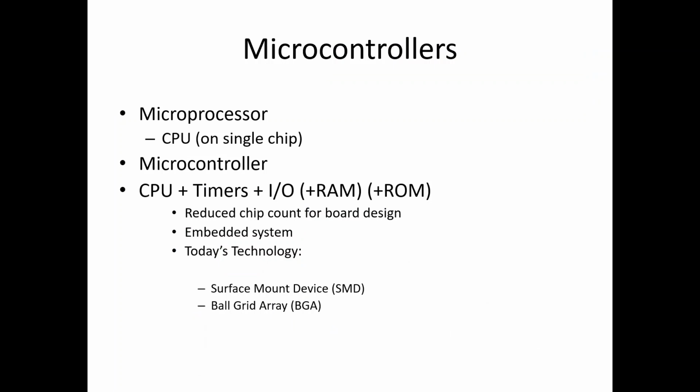As for the types of microcontrollers, we could categorize microcontrollers based on various criteria. First is the architecture. Under architecture, we have the Harvard architecture, with separate memory spaces for program and data, allowing simultaneous access, and the Von Neumann architecture, with a shared memory space for program and data. As for the data bus width, we have 8-bit, suitable for simple control tasks; 16-bit, which offers a balance between performance and complexity; and 32-bit, used for more complex applications requiring higher performance.